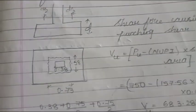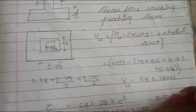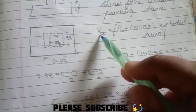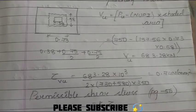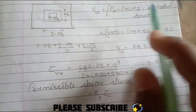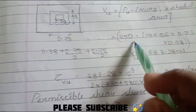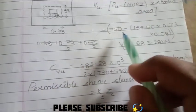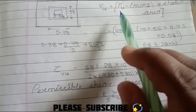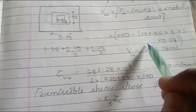Here the shear force we are considering is the punching shear. To calculate the force, we have to multiply the stress by the area. That's going to be Pu minus Nu Pi. So this is going to be the stress, guys. Whatever the Pu minus the Nu Pi, this is the value of the stress multiplied by the area.